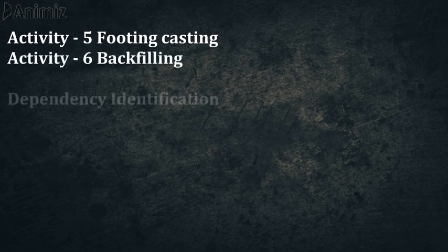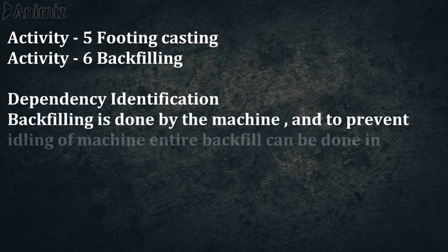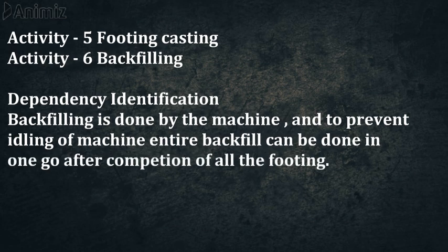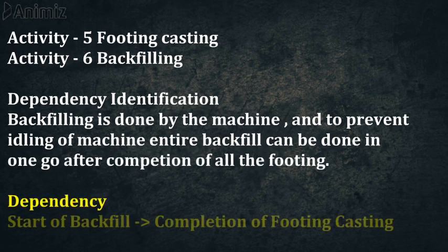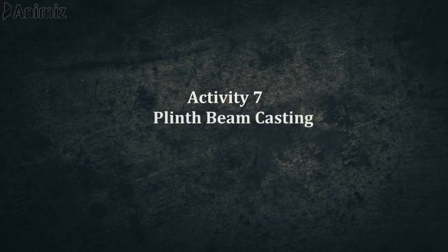We do the backfilling. So now how is backfilling dependent upon the footing casting? Backfilling is done by machine, and to prevent idling of the machine, the entire backfill can be done in one go after the completion of footing. So we can say the start of backfill depends upon the completion of footing.